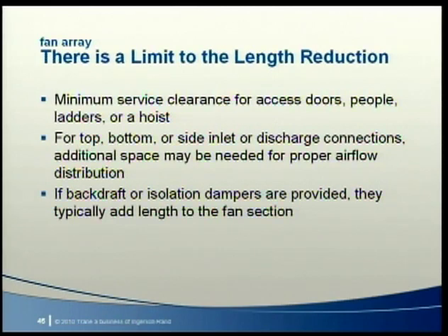Finally, motorized control or backdraft dampers are sometimes used to prevent backflow through an inactive fan. Isolation dampers on the discharge side may be provided to allow a fan to be serviced or replaced while the other fans remain operational.